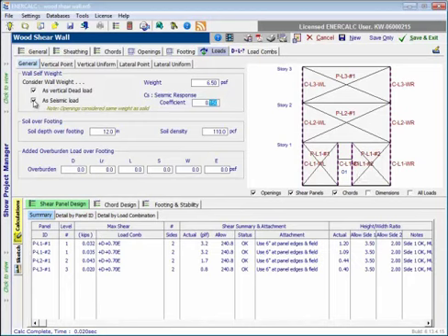Now the other thing I'd point out is that you don't have to use the wall weight as seismic load. Perhaps you've got reason to apply those loads in a different way. You can simply deselect that option and notice that the CS value input goes away. And likewise, maybe you've already made an allowance for the wall self-weight in your applied loads that you're going to use on these other tabs. You don't have to have the program automatically consider the self-weight of the wall framing. You can just turn that off, and even that input goes away, just to neaten things up a little bit for you.